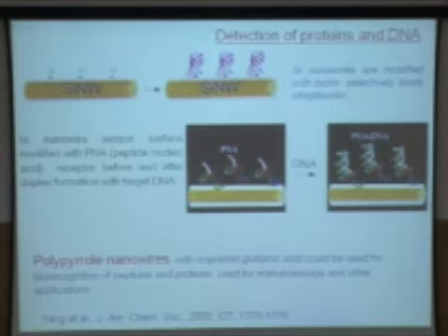But what you have to do is, on the nanowire, you have to put some molecule which recognizes the molecule you want to detect. So this is a process called biorecognition. So you have a silicon nanowire. On that you put a molecule which will detect the virus which you want to detect. So it will latch on to that virus. And when that latches on, some property should change. It should be either conductivity or its photoluminescence or something like that.